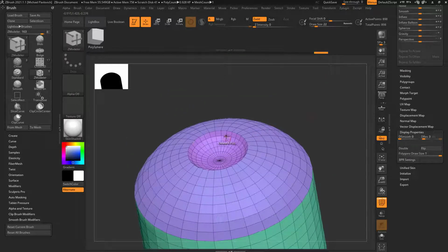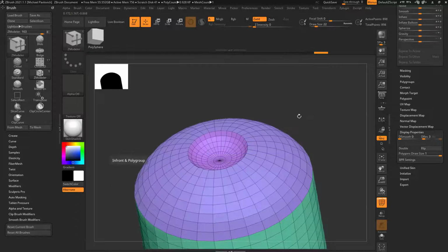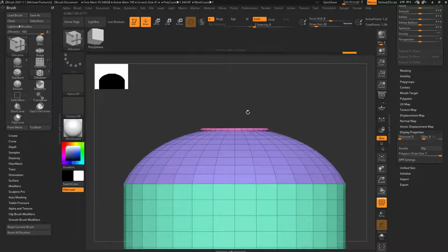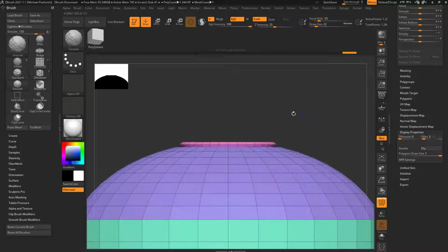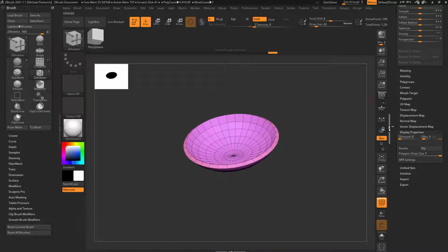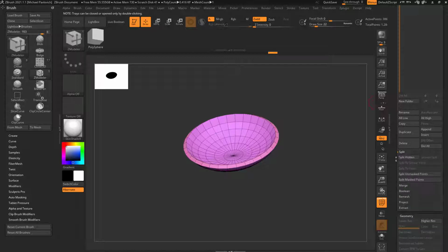So now at this point, again, there's so many things you can do here. You can hover over a face, say Q mesh, polygroup all, hold down Control, pull out a copy of this, continue to Q mesh this. And if you want to split this into its own subtool, you can. Hold down Control Shift, go to select rectangle and select it, and then do subtool, split hidden.